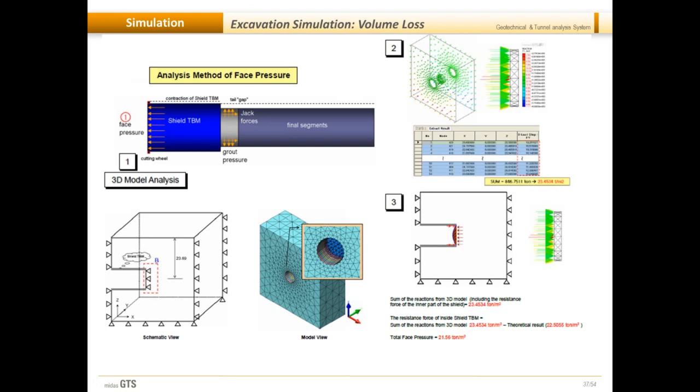So let's say this is the face pressure profile. So instead of this, if I can control my tunnel boring machine and angle and the face alignment, and let's say if I want to increase the efficiency, I want to have a different pressure distribution, I can control that. So here we are not assuming the out of plane behavior. Here we are controlling them by applying the accurate force value and simulating to see what and how it's going to affect our excavation sequence and thus the ground behavior.